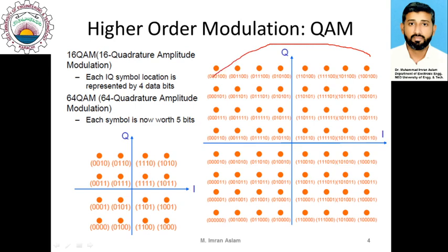On the right side we have a constellation of 64 QAM symbols. So there are 64 total possible symbols, and you can see that each symbol has a different phase as well as a different amplitude, and in order to decide any symbol at the receiver side, we would need the information of amplitude as well as the phase.